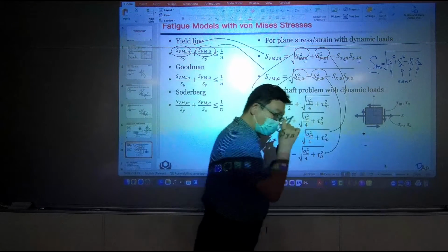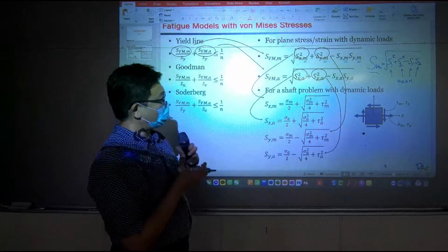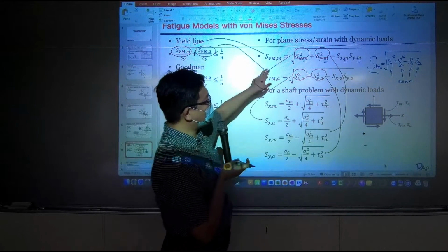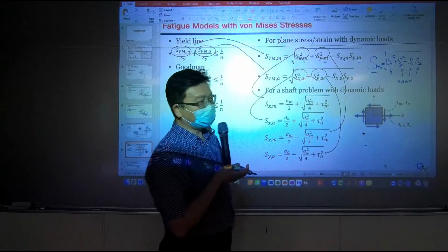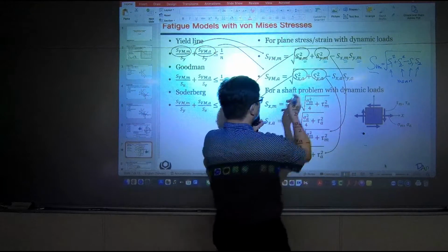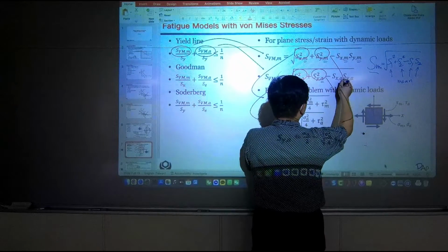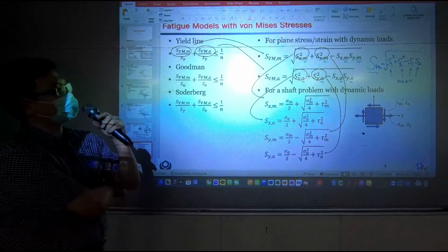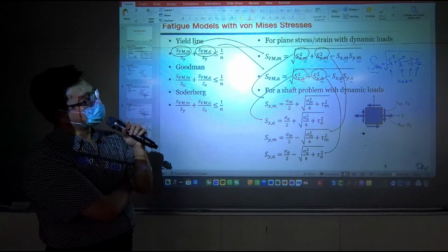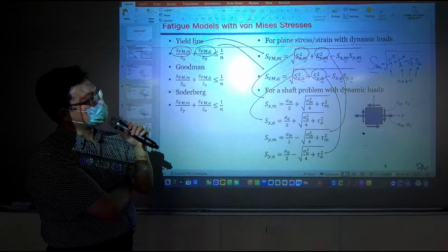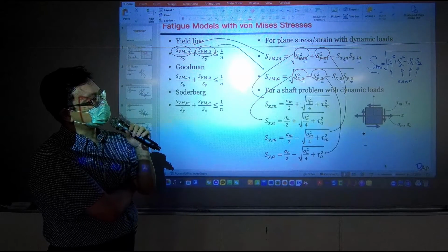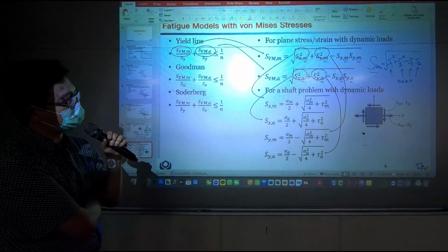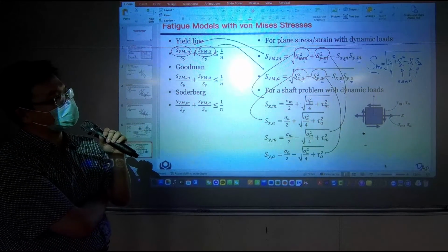So in the problem, you can study the mean of your principal stresses. Just plug in. Then you can analyze the mean of the von Mises. And also for the amplitude, just plug in. This is the easiest way to estimate it. Is it always correct? Let me see if there's a special case when it's not correct.